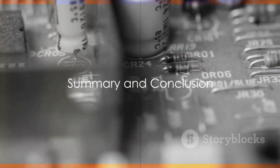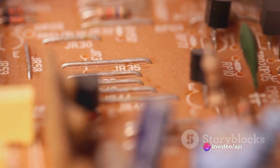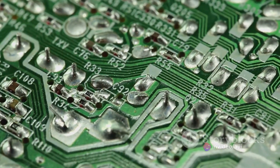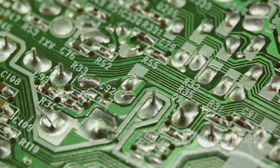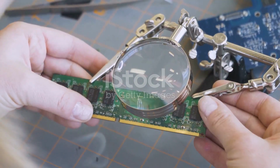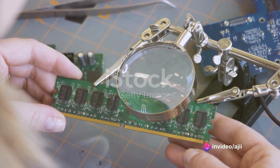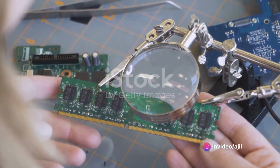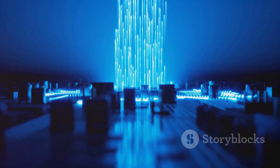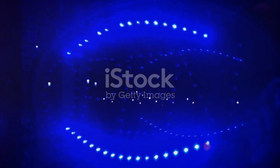So, let's quickly recap what we've learned today. Diodes, those little components on our workbench, are more than meets the eye. They're two-terminal devices acting like electronic check valves that allow current to flow in one direction while blocking it in the other. This fascinating behavior is due to their unique semiconductor properties with N-type and P-type regions and a middle depletion zone that acts as a barrier to current flow in reverse bias. In forward bias, however, diodes let current flow freely.